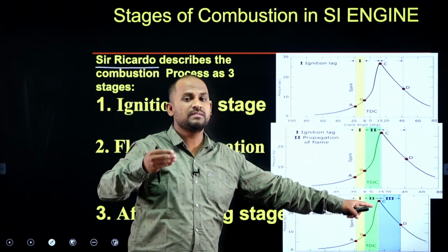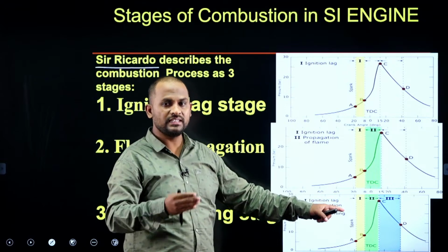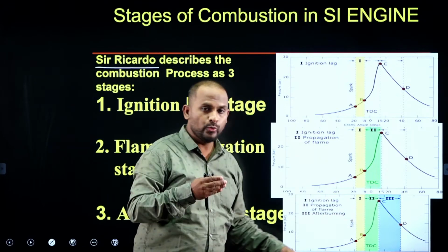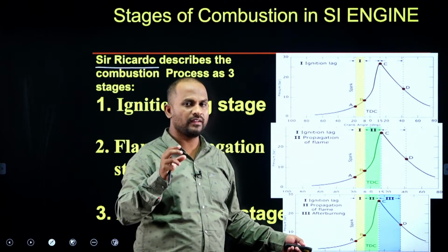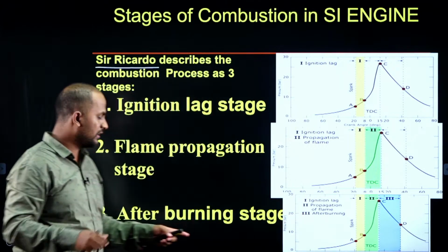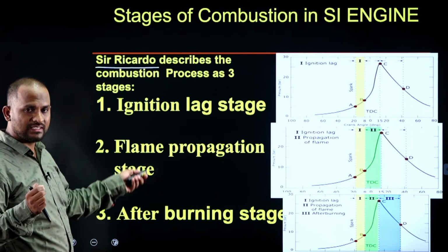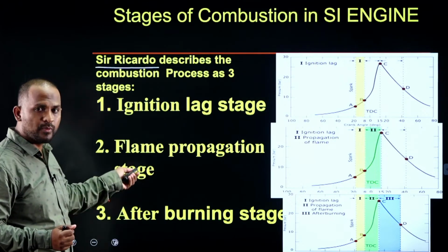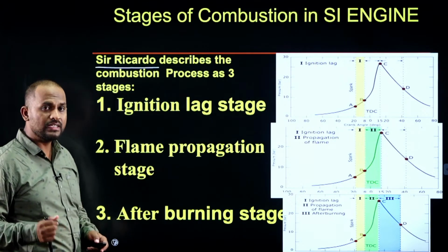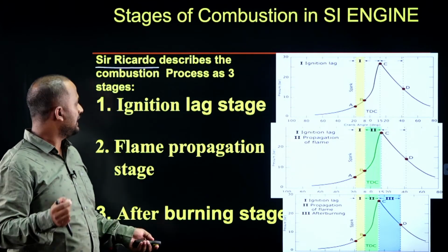Now coming to the third stage, after reaching the maximum pressure, the piston will be moving towards the BDC, which is called the expansion stroke. During that stroke, if there are any fuel particles left, they will be burned. That is the third stage, called the after burning stage. Now these are the three stages in SI engines: ignition lag, flame propagation, and after burning stage.